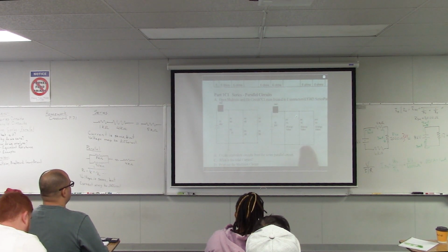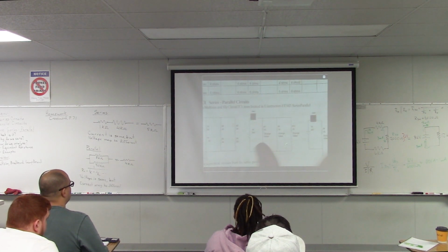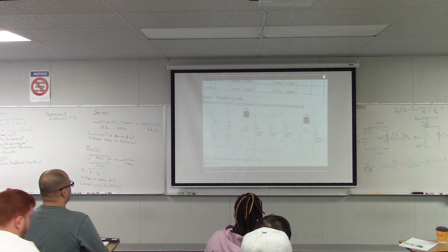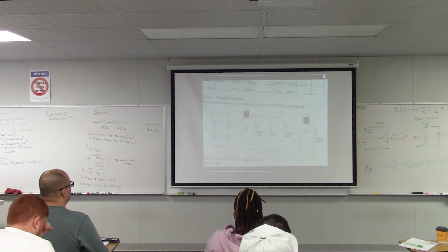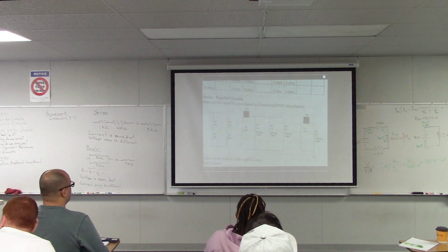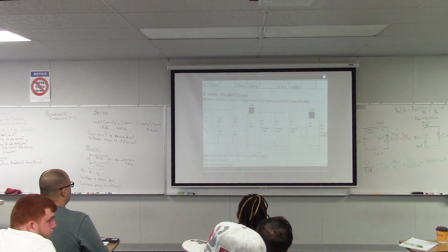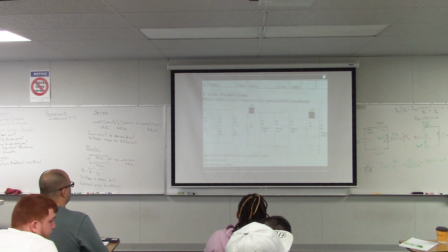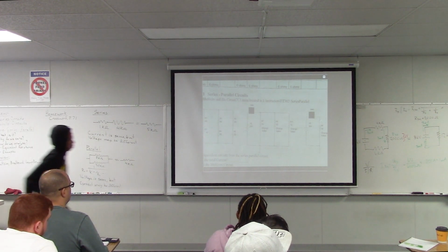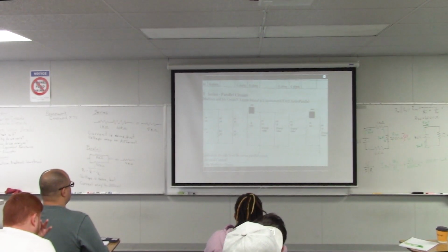So you can redraw all of these 3 resistors as just one single equivalent resistance. So that's what we have over here. So they've been all redrawn with one resistance. Again, we have kind of a 1 ohm placeholder value, but you're supposed to change that value to whatever parallel resistance you calculated from the previous circuit. Now, if you've done your math correctly for all of these, their resistances should all be equivalent. And that means that the current flowing through each circuit should be the same.